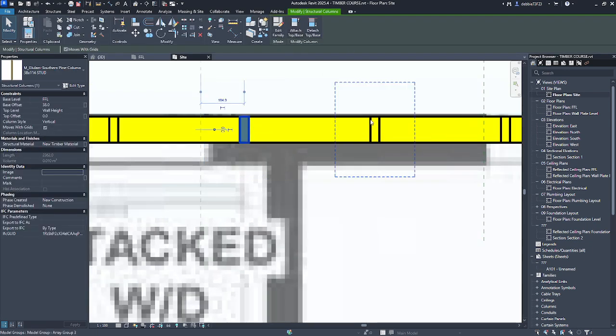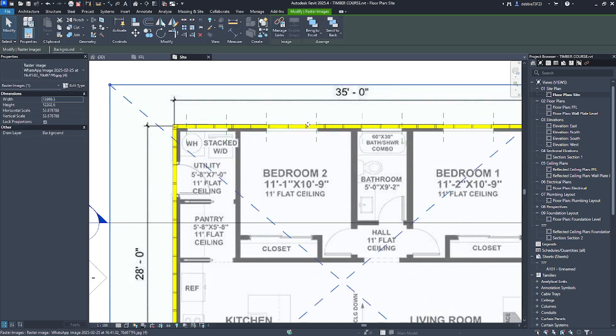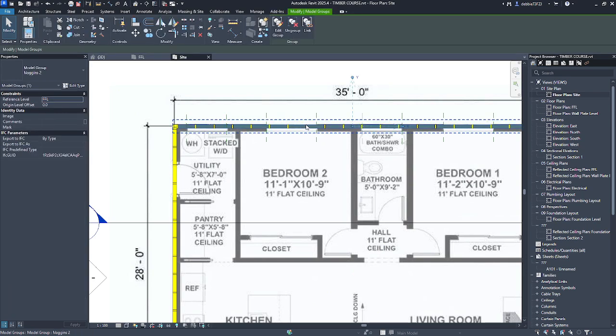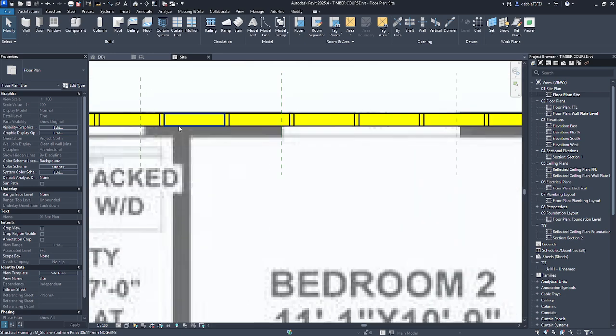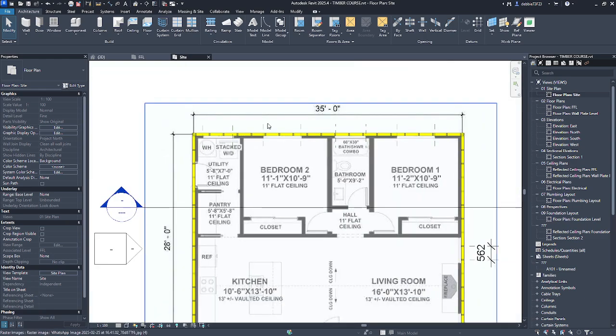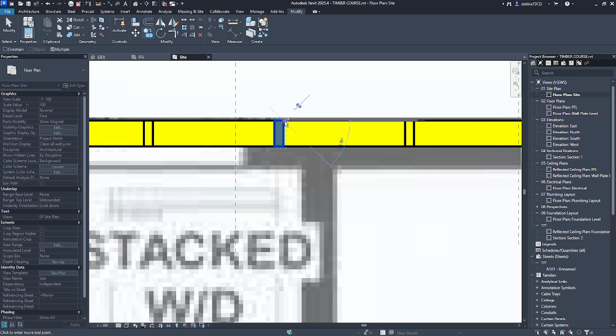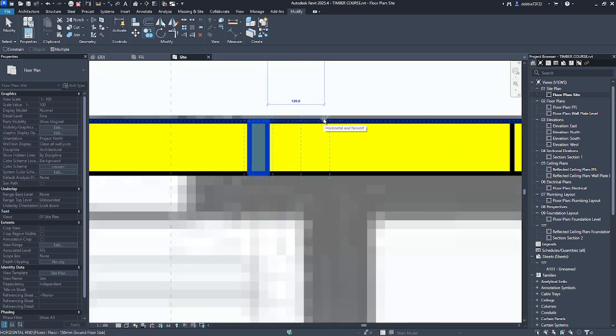So let me just ungroup these studs from the previous class with our array. Ungroup. Let's start with this corner. So all our main studs are centered. So we're going to use our 38 by 114 stud again. So on your keyboard, CO for copy. We'll just move that in. Let's put it at 120. Let's put another one.